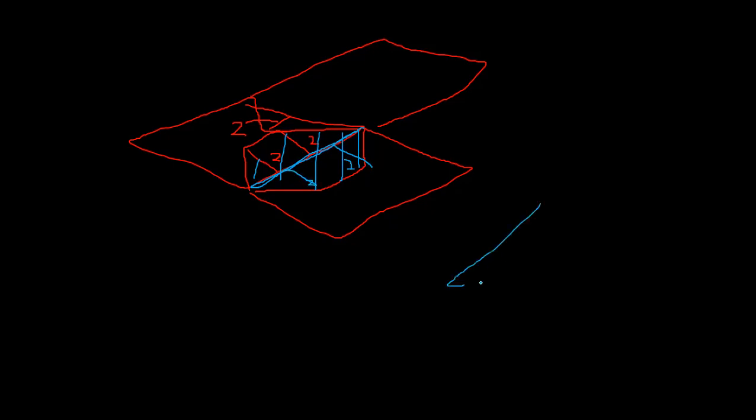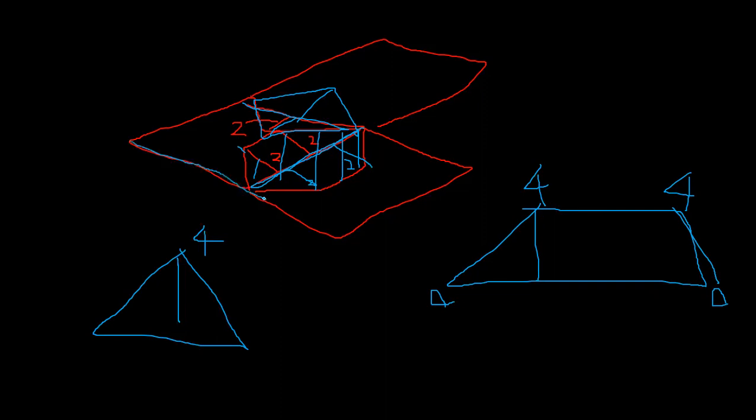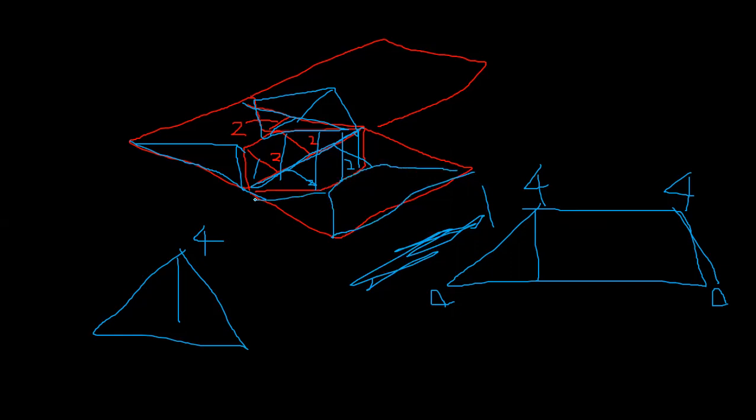So the total height of that UDL is going to be 0 at the ends, not going to change. But this height 2, this height 2, it's going to be 4. And for this triangle, this side 2, this side 2, so that's going to be 4 as well, right? This is only for interior panels. If it is at the edge, only that load will be there. No panels here and no panels here, right? This is the edge panel. Edge panels, you only have one contribution, right?